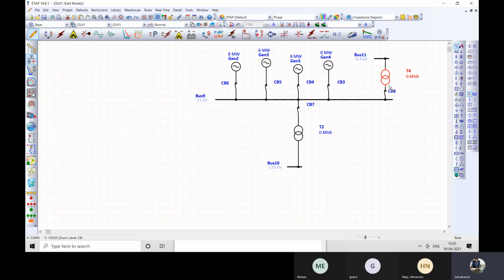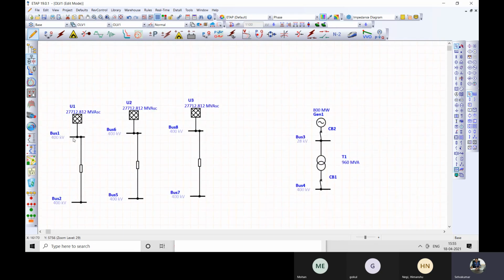Then one important dimension we need to really look into is what fault current we are considering, and whether that fault current is coming from transmission lines or from a source like a generator, because this fault current contribution and this contribution are completely different. When it is fed by multiple transmission lines, that means it has a significant capacitance, so that plays a significant role. Whereas if it is something like this, then it really doesn't have any significance. So that's what we need to look at.